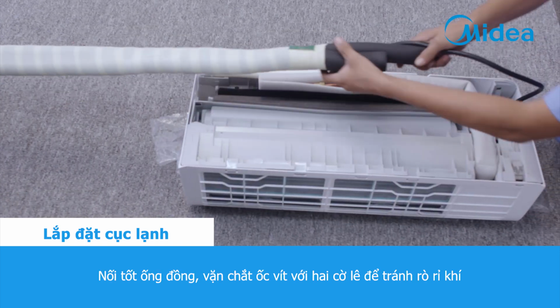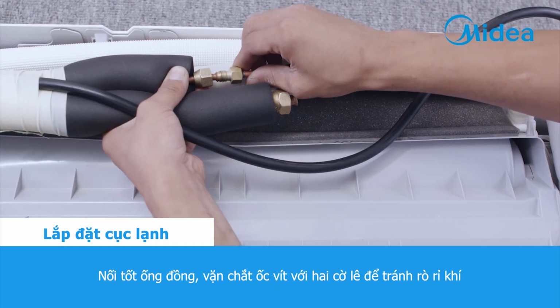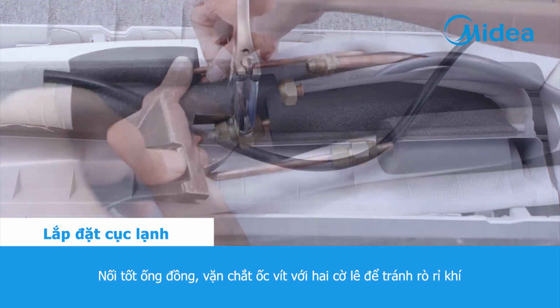Make good connection of copper pipes. Fasten the nuts with 2 spanners to avoid gas leakage.